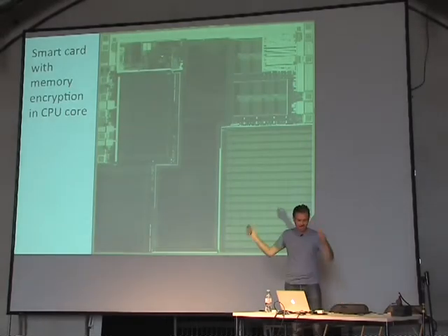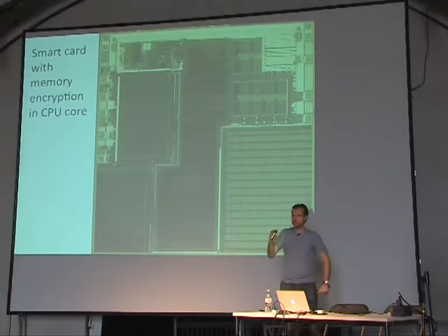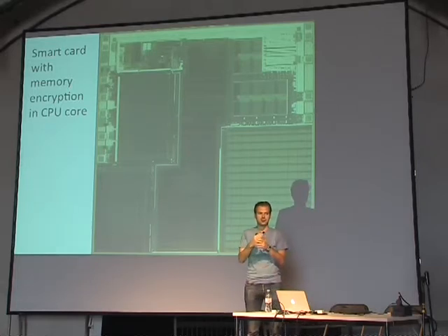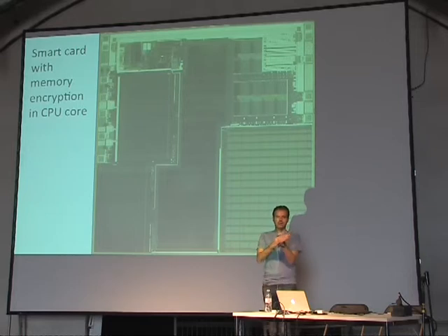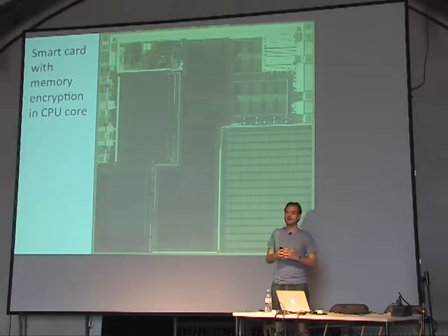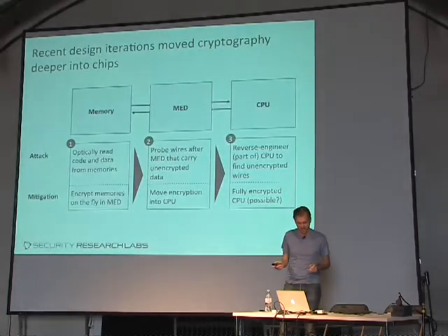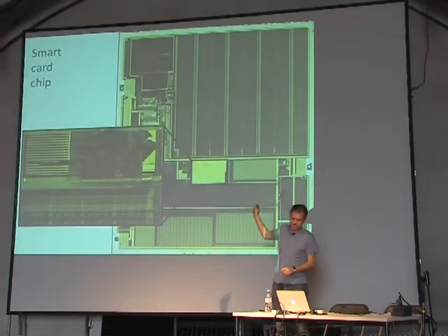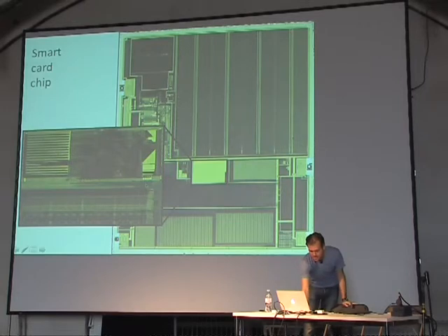This smart card here, also an optical picture, so it's probably something like 200 nanometer, right? 180 nanometer is the edge, the last possible size that you can picture optically. Everything underneath, the wavelengths of light are too big, so optical microscopes don't see the gates anymore. However, even in a 180 nanometer chip, the upper layers, of course, are much bigger structures. But everything 180 and below, you will need to use a scanning electron microscope or a FIB, at least for a few layers.